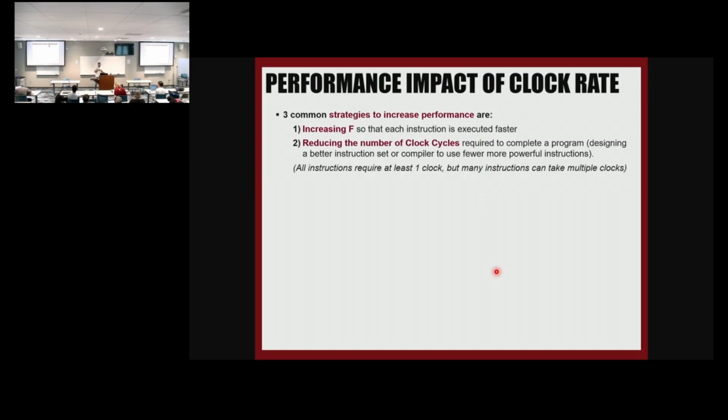So one research that we do in our lab is in-memory computing. In-memory computing does vector matrix multiplication. What we do, we design the vector matrix multipliers. It's a pretty large system. Instead of having just one multiplier, you have a block that does the entire vector matrix multiplication. But then you add one instruction to the instruction set architecture, and you can say, do vector matrix multiplication. So now you can do vector matrix multiplication in 1 clock cycle because you have a hardware for it somewhere, right? So that's the whole goal.